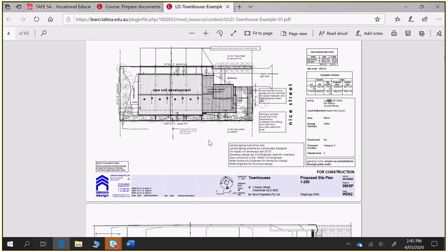What level is too low to be able to go to the street water table? Is it the gutter line that affects it? Yeah, so it's the gutter line, but you'd want to set it about 500 mil below the gutter line because you need some fall. You need 1 in 54 or something, 1.65 degrees or something, from your gutter. My take on it would be that it's actually a terrible waste to be discharging it to the gutter when it can go to a natural watercourse. If you've got a gully down the back and it is actually a natural watercourse, you may as well be discharging it to a natural watercourse that they don't have to manage. Yeah, council would probably see it like that as well.